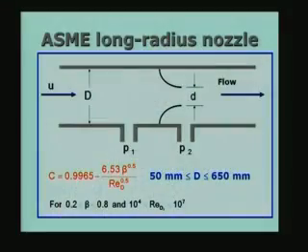Therefore, depending on the application, depending on the velocities which are achieved, you may choose different values of beta, or choose the appropriate value of beta such that the pressure difference is easily measurable. So, that is the reason why we have different values of beta, and you can choose anywhere between 0.2 and 0.8 for this particular case as I have indicated here, which is also true for other devices.